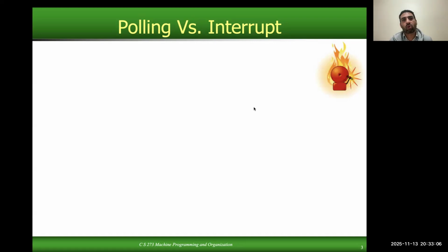So this is one approach, and this is known as polling. We are continuously polling or checking a certain bit. And by we, I mean the microcontroller. So when the microcontroller is doing that, it is continuously running in the loop. Let's say that you initialize the register with 0 and it is an 8-bit counter. So it counts to 256.